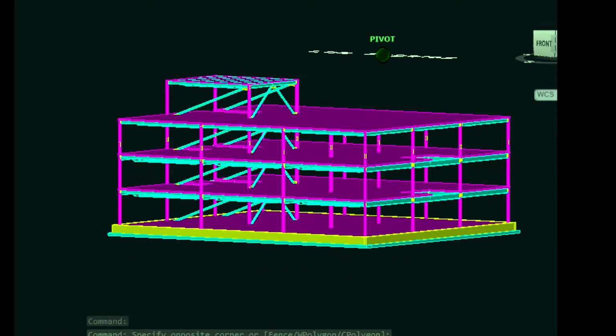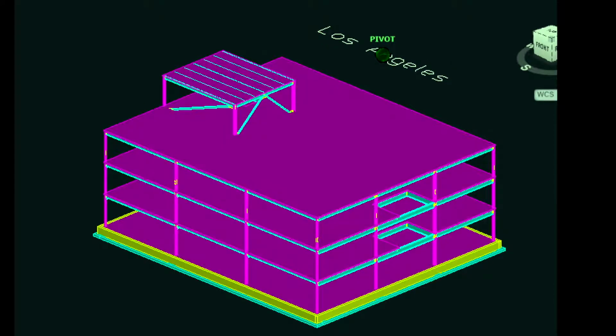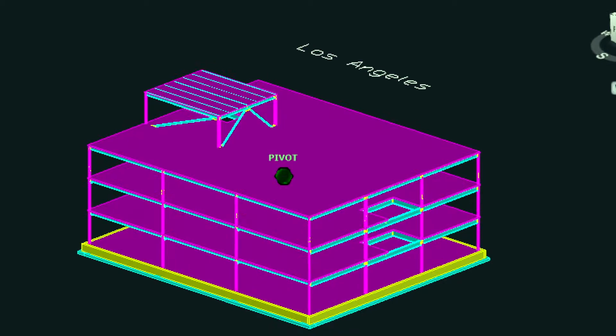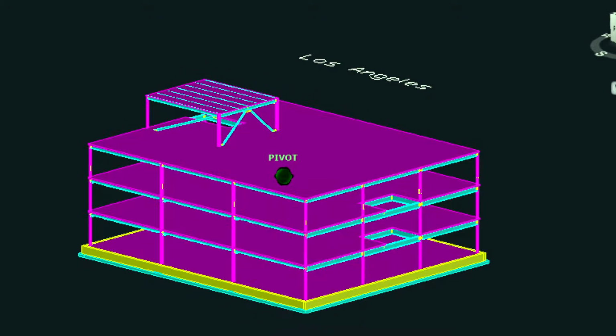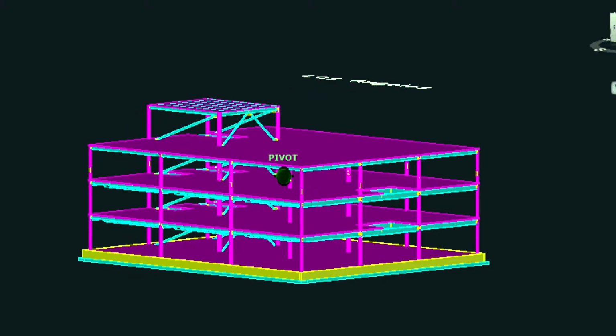Hi, I'm Frederick Cernattinger, and talking about these loads, the wind and the seismic loads were used in the calculation of the demands on the brace frame members for both the east elevation and the south elevation. And for the beam and column calculations of the demands, the live, the dead, the wind, and the seismic were used on both elevations as well. And then the elevation that had the max load on it was chosen as controlling, and thus the design followed